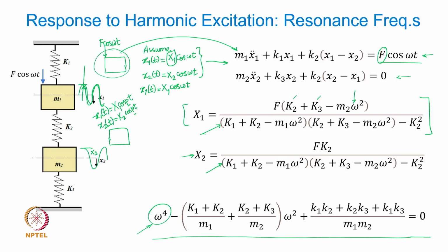And from the single degree of freedom system case, you already know what that is called: resonance. When the value of omega 1 is equal to the natural frequency, you will have resonance. Now you have two natural frequencies, so you can get the second of the two frequencies from this frequency equation, which will correspond to the second natural frequency, and that basically is the resonance in the 2 degree of freedom system when it is subjected to a harmonic excitation force.